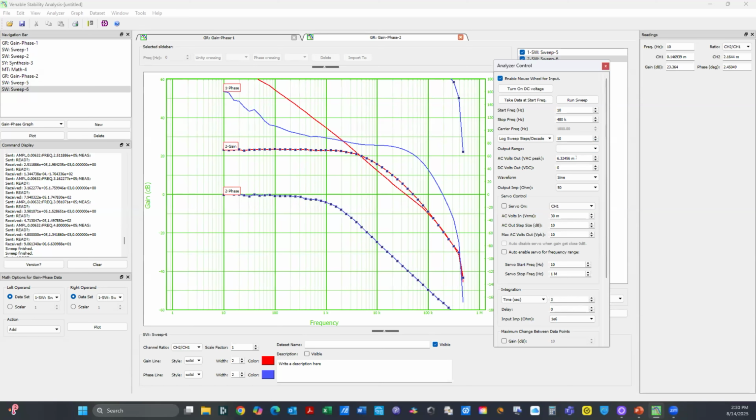And then right here we have the AC volts. I'm usually setting that to around 40, say I'll put 40 millivolts in here. Since we're directly connecting to the power supply and we don't have a step down transformer, you really don't need to inject that much signal to get a decent plot.